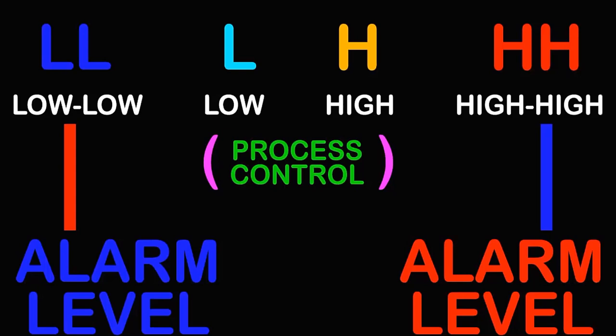Likewise, sometimes relays stick, and generally when we're energizing an output from our PLC, that output signal is actually going to a relay which is controlling the higher voltage and or higher amperage, which is going to the actual device itself. And perhaps our output to the heater has de-energized, but the relay was stuck closed, in which case the heater, even though there was no output signal from our PLC, still had power and kept heating.